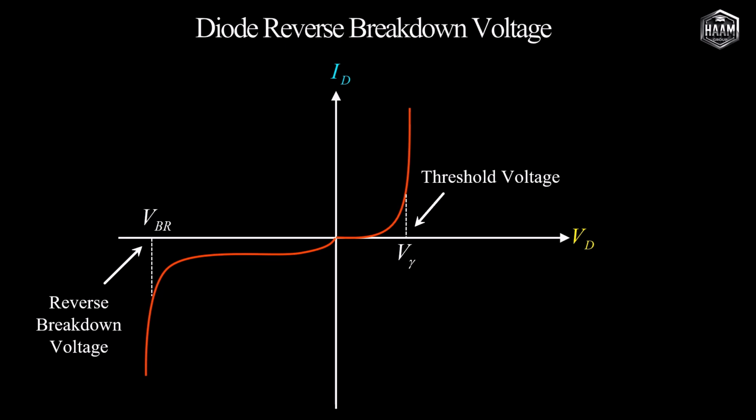For instance, breakdown voltages are commonly cited as 50 volts, 100 volts, or 200 volts, all of which correspond to the negative voltage region. At this voltage, due to avalanche and Zener breakdown phenomena, a substantial current can flow in the reverse breakdown condition, and the slope of the current curve increases sharply at this point.